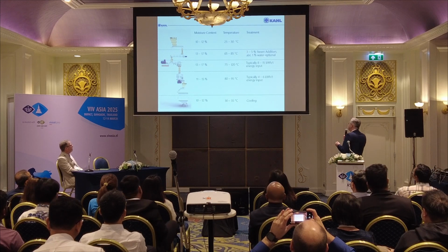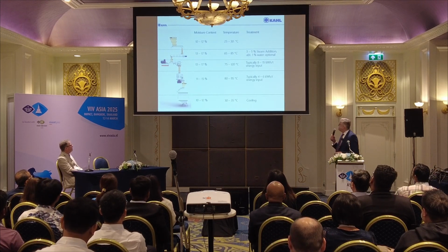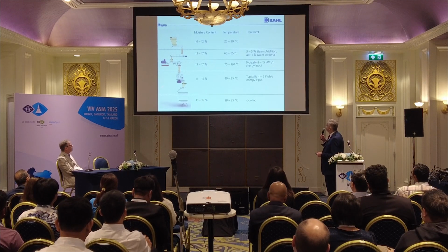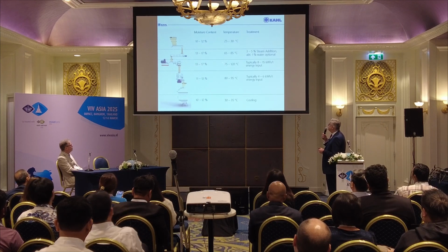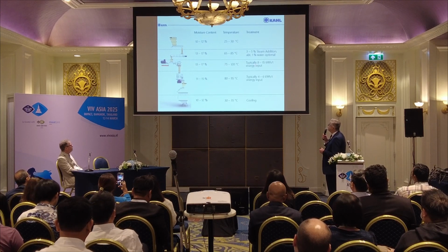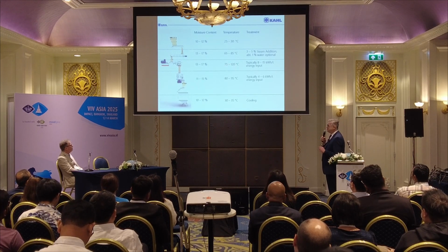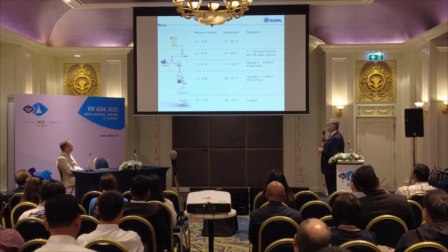It remains basically the same. And we have the option to add 1% of water, because an expander-processed feed is non-sensitive to moisture. So we go into the expander with 13 to 17%, and then we put mechanical energy in and reach an outlet temperature of 75 to 120 degrees. This depends a little on the animal. Pig feed starts at 75.